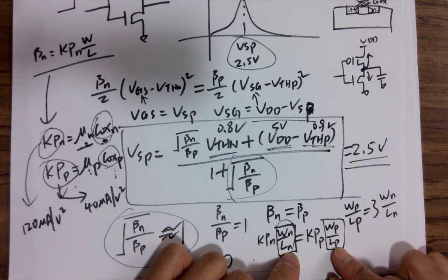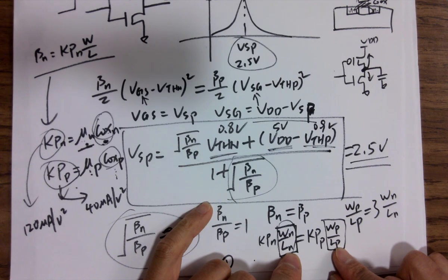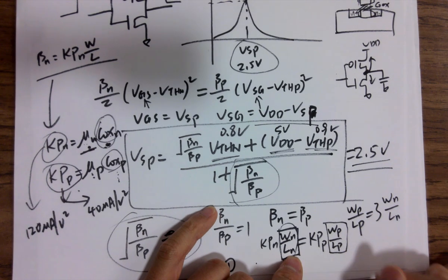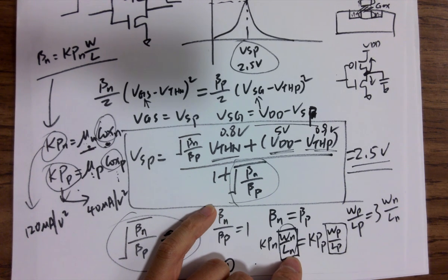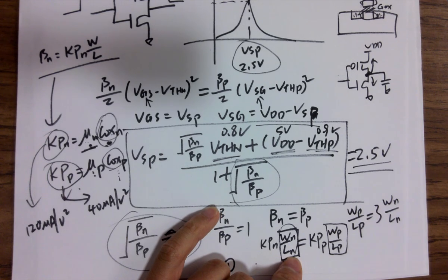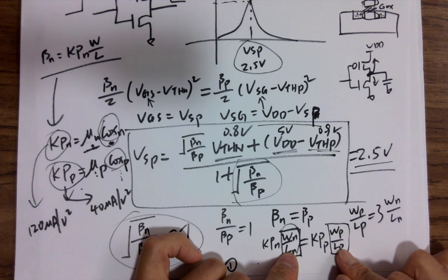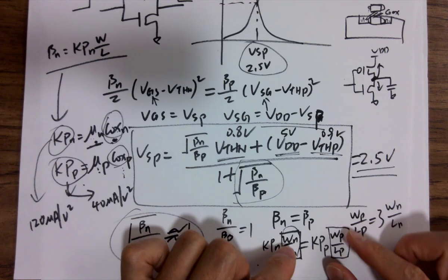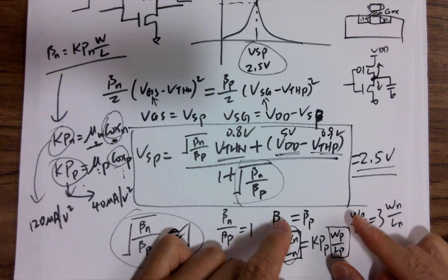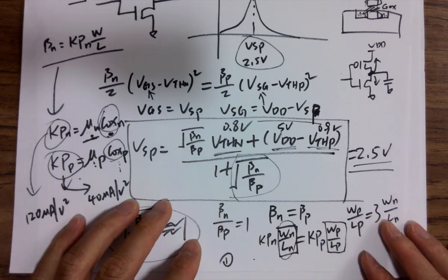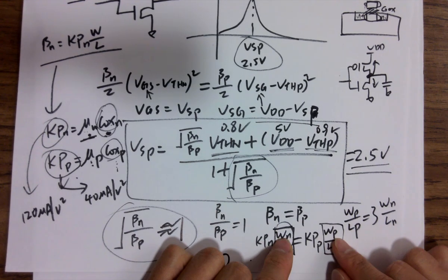Remember why? Because C5 is 500 nanometers as a minimum length, and we want to improve the yield, so we don't want to exactly use the 500, the minimum one. So we increase it a little bit by 100 nanometers. So the minimum we should use is actually 2 lambda for length, and we don't want to modify it, because eventually the current is not determined by the individual length or width, it's determined by the ratio, right? You don't want to increase the dimension too much. So keep the minimum length here. So the only one you are modifying is actually the width.